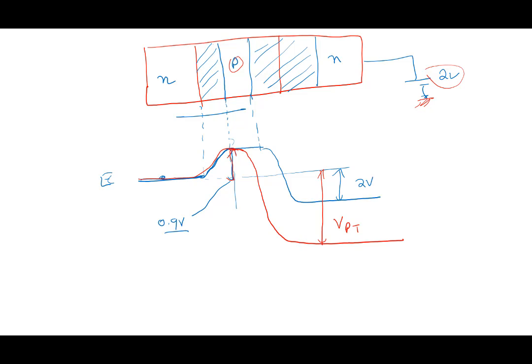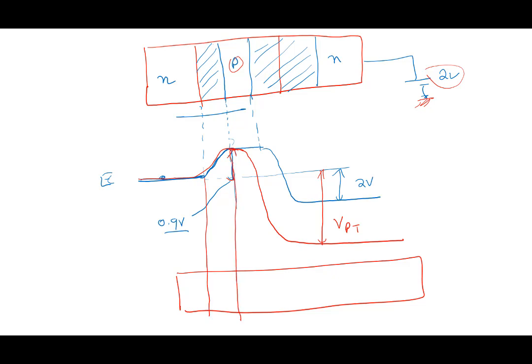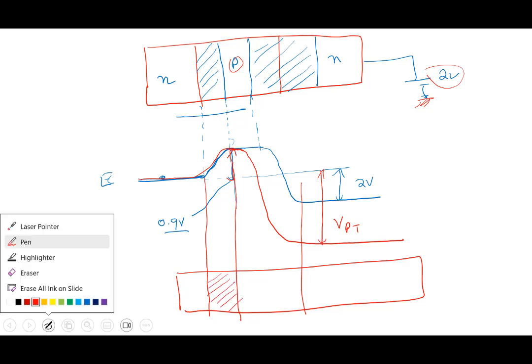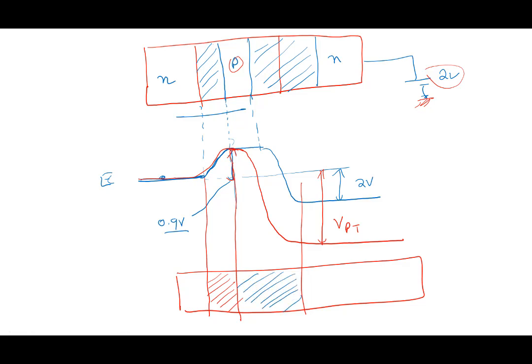Note that the two have already touched. So this is the situation. This is the one edge, this is the other edge. From one side is one depletion region, from the other side, the other depletion region. The two depletion regions are already touched. So now what will happen? You've applied more collector voltage, so the collector needs charge, and it will try to eat into the other one. It will try to take the charge from the other one. At some point, we can solve a problem like this through Poisson's equation and all that.